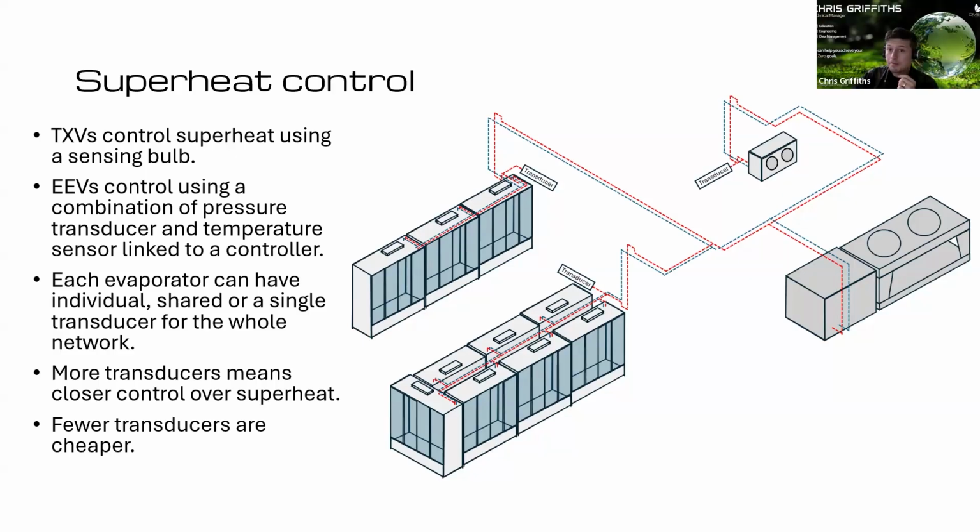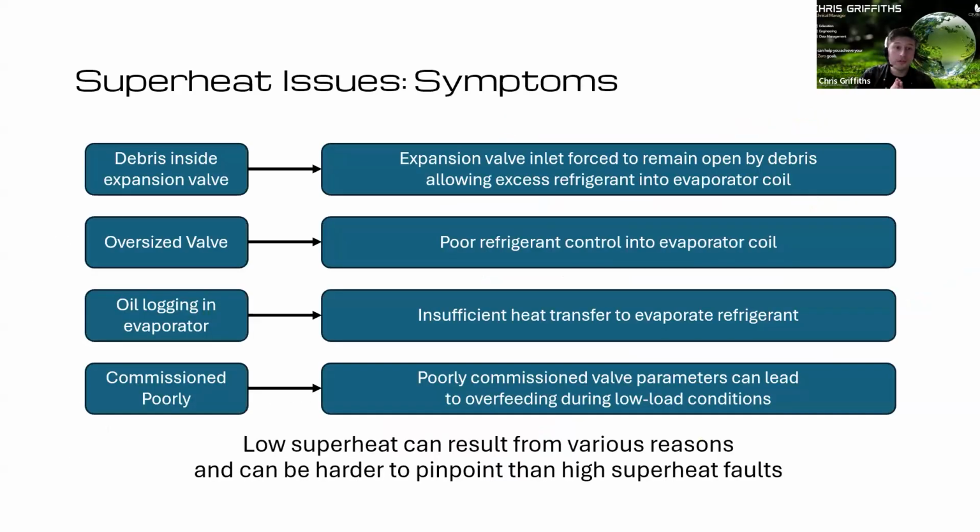Sorry, something just to jump on that, we'll look through it in a minute, but one of the issues we've encountered in the past with those controls, sometimes it's buried deep in manufacturer's literature, is that say you have a 60 bar transducer versus a 90 bar transducer, you need to go into the controllers and set up which type it is. Otherwise it will not read correctly and you will get funny values and discrepancies. The system just will not work as it should, which can lead to some not catastrophic failures, but definitely some big issues that technicians could do without. So make sure it's commissioned as per all the manufacturers' set points and recommendations, and obviously a key one to drive home.